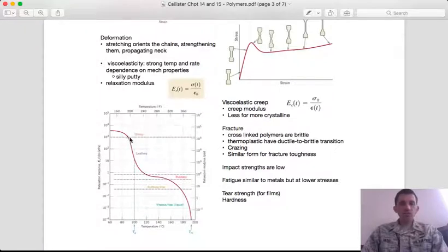As you increase the temperature, right, polymers pass through various stages where they have more mobility of the polymer chains. So you have kind of this leathery stage where you have a drastic decrease in the relaxation modulus, and then transitioning to a rubbery, and then a kind of a very flowing regime as you go up in temperature. And I'd point out that these temperature changes here are not very wide, especially on the scale that we would think of with metals or ceramic materials.